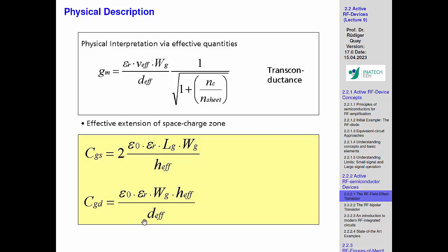So these two cancel out. So the feedback capacitance is essentially a constant, which is nearly true. You can discuss that, but it's a very weak function. So the feedback capacitance is just metals. Yeah? So that's the main problem.